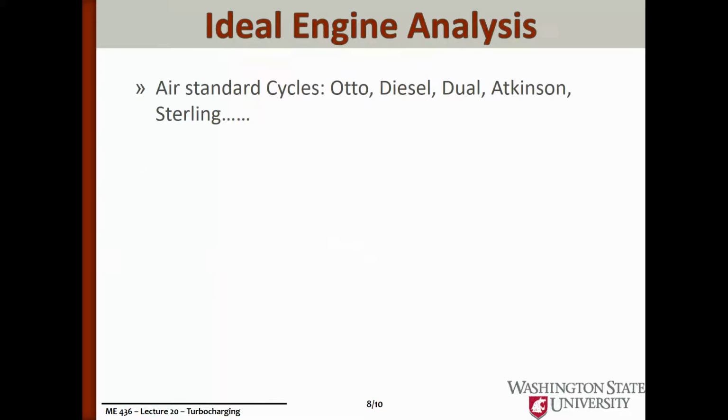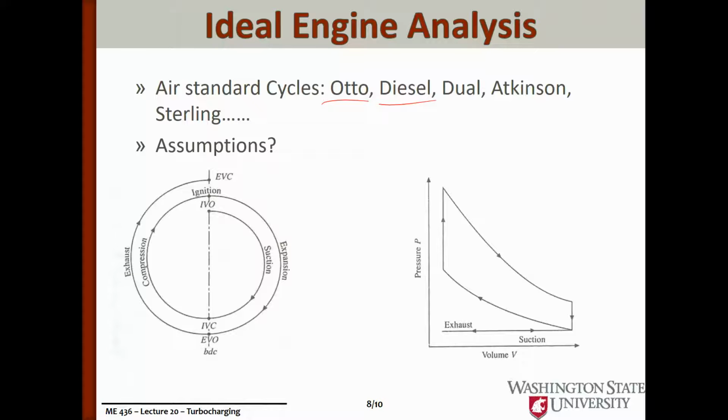I want to briefly recap what we've done in this course. We started with ideal engine analysis. We worked through Otto cycles, diesel cycles, dual cycles even. And what assumptions did we make for those? Well, first off, we typically did the cold air standard analysis. We assumed combustion was instantaneous in the Otto cycle. We assumed sometimes no pumping work.